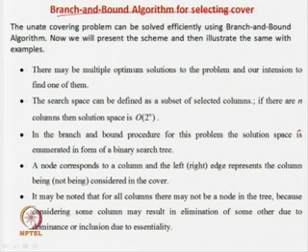There will be solutions corresponding to the leaf nodes, in fact multiple solutions, and you have to take the one which has the minimum weight. And how are weights assigned? A very simple weight can be the number of prime implicants involved. All the prime implicants have equivalent weight, and if you count them, the solution having the minimum number of ones is the best. All zeros means no prime implicant is selected, all ones means all the prime implicants are selected. So for every prime implicant selected, you add 1 to the weight. One prime implicant means weight 1, two prime implicants means weight 2 and so forth. If you add up everything, it will give you the weight.